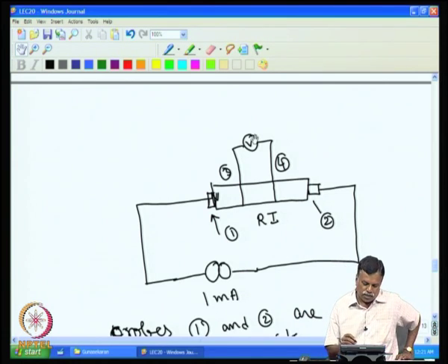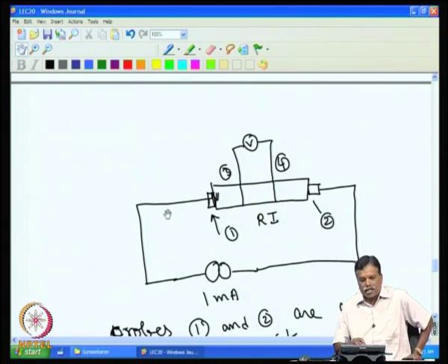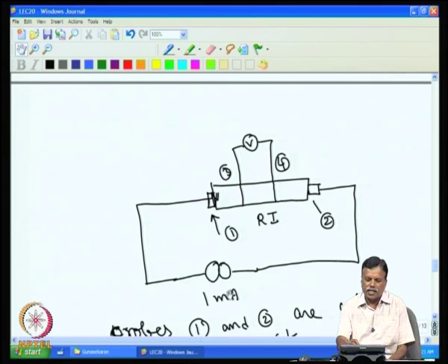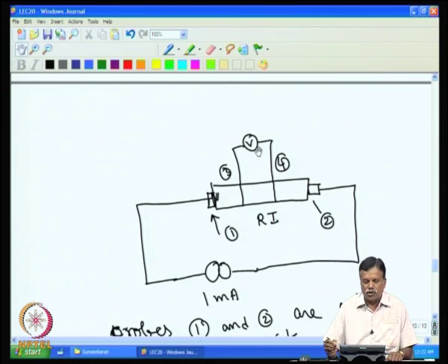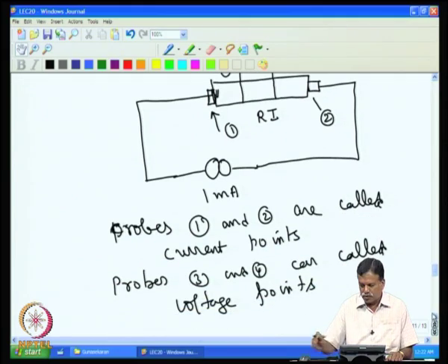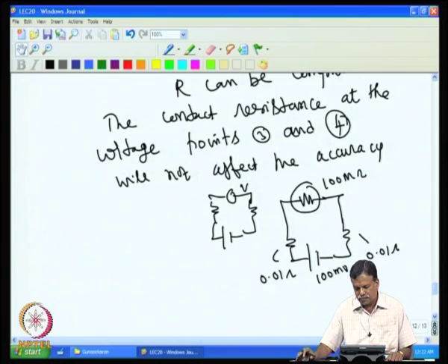So, for low resistance, the 4-probe method is good, provided one takes care of the error due to this current and the error due to the voltmeter, which is normally not possible. So, you will have accuracy much less than the bridge technique. However, for lower resistance, there is no option other than using this 4-probe method. So, for all low resistance measurement, the 4-probe technique is used.